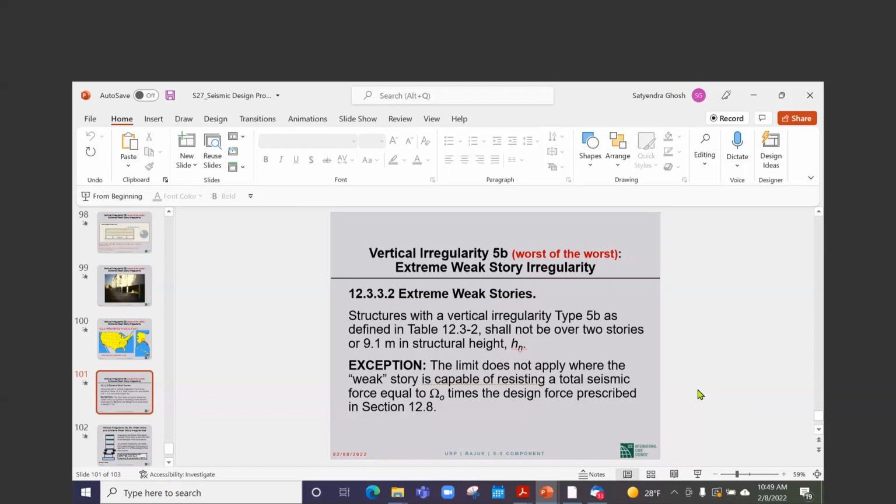As the openings get smaller and smaller, you tend to approach a shear wall core, and that would be an R of 5. So this is one of those undefined systems where you will have to exercise your judgment. It will be somewhere between 5 and 8. I will tend to take something like 6.5, no more than that. But this will be only designed up to design category C. I want to emphasize that design category D, you cannot do it.